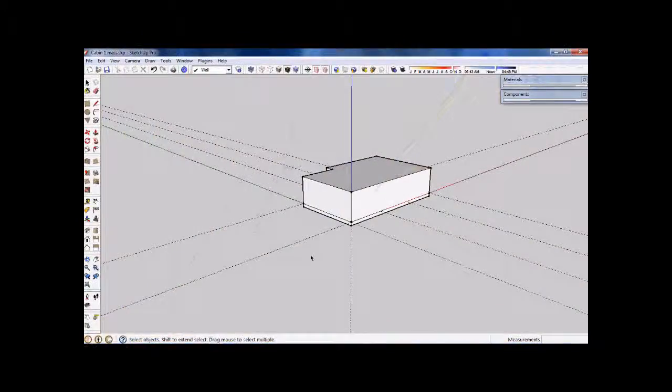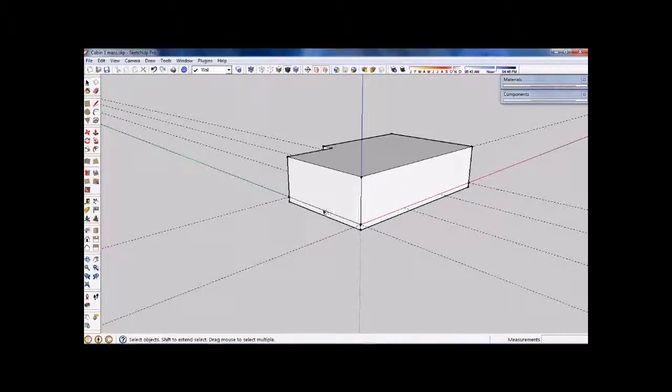Okay, so here's the building shape we've got so far. Even though, when we pulled the floor up to create the height of the walls, we were in the wall command, because we were push-pulling an existing entity which was made on the floor layer, not the wall layer, it maintained its parent relationship with everything else that we push-pulled up.